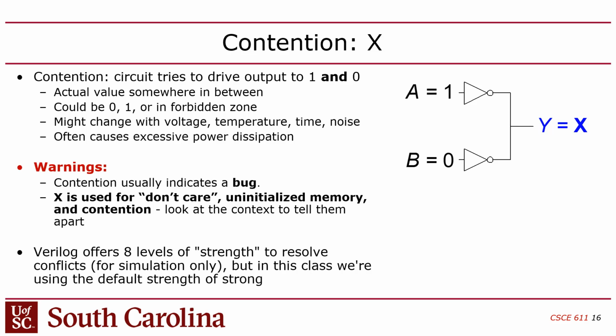No, it doesn't, because those equivalent resistances limit the current. But the voltage of that wire ends up somewhere in between power and ground. You end up creating a voltage divider, essentially. Say your supply voltage is 2 volts, and you have one gate pulling up and one gate pulling down.